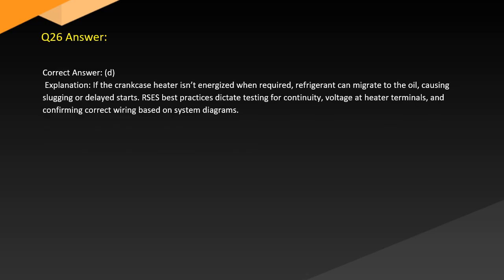Answer. Correct answer: D. Explanation: If the crankcase heater isn't energized when required, refrigerant can migrate to the oil, causing slugging or delayed starts. RSES best practices dictate testing for continuity and voltage at heater terminals and confirming correct wiring based on system diagrams.